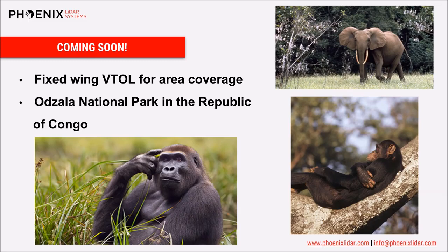But this fixed wing VTOL, first and foremost. Our area coverage and really our efficiencies are pretty much limited to multi-rotors right now. We get 25 to 30 minutes of flight time with our new Alta. We've also picked up efficiencies in processing with fewer flights, because one of the slower ends of our processing chain is the actual trajectory processing, and the more flights you add, the longer that takes. So we wanted to cover more area than we currently can, essentially in fewer flights, so we have a faster processing chain.